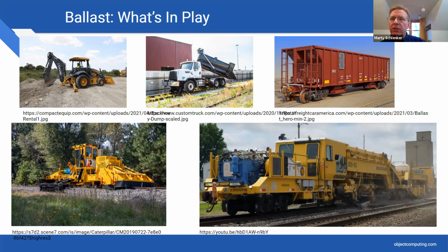Railroads do it today basically through expertise alone, and that's something that cannot be dismissed in a production system that would give guidance to railroad experts. But this is what we got. These are the assets that we have to deploy to ballast management. And this doesn't even fully cover it, right? Because you also have shoulder ballast cleaners and undercutters that are more targeted towards removing fouled ballast conditions and replacing the fouled ballast with clean ballast, which can then become fully supportive of the track.